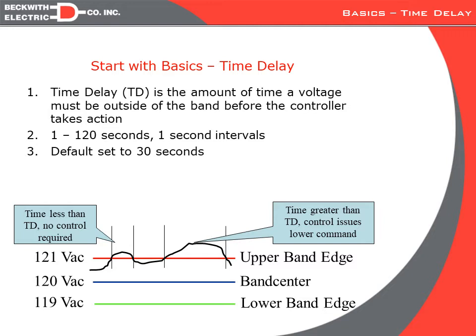But once the air conditioner gets up to rated speed, the voltage will come back up as the current goes down. So if we were to have many air conditioners coming on at the same time, we would see a temporary voltage drop, which may cause us to want to lower the voltage. But if we did that, we would just have to raise it again once they all got up to speed and they started drawing less current. So the nature of motor load is such that as it starts up, it requires more torque, therefore more current, which can create a voltage drop. And we want to try to ride through that voltage drop before we attempt to correct it, and that will save us operations on the regulator or the LTC.